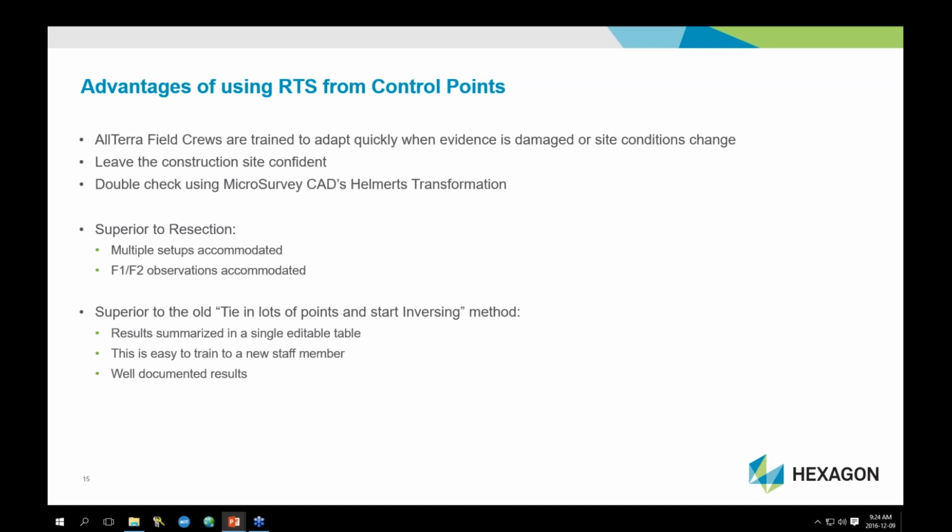With a resection, they can start with 3 points or 4 or whatever, and they get going, but if they find the resection was wonky, they can't tighten up their work that easily. With this tool, we can rerun the function, discard the post that turned out to be out of position, and tighten up our searches.